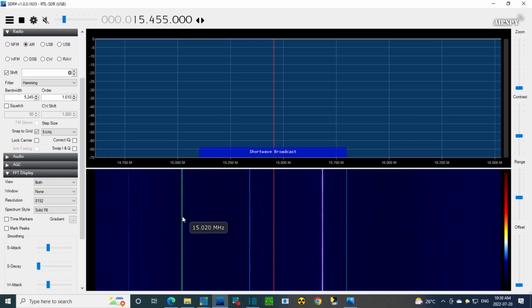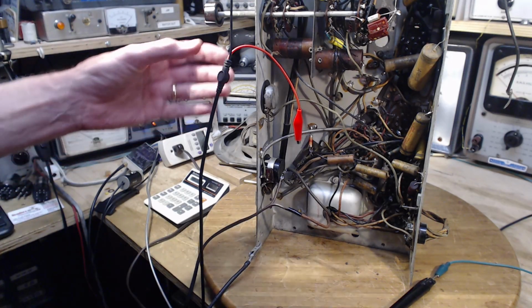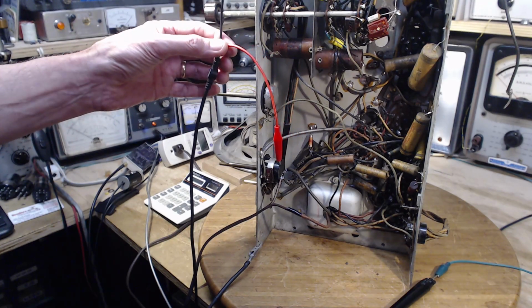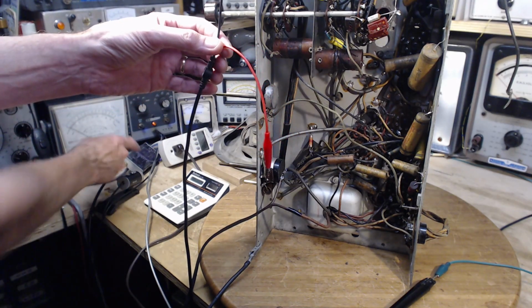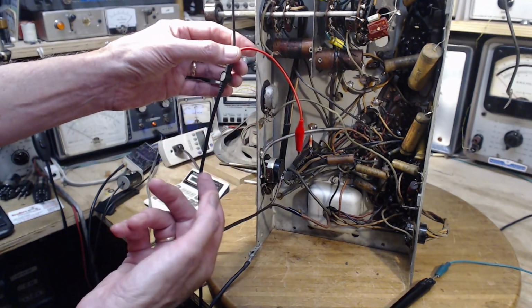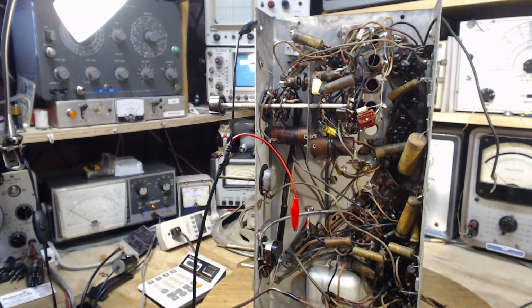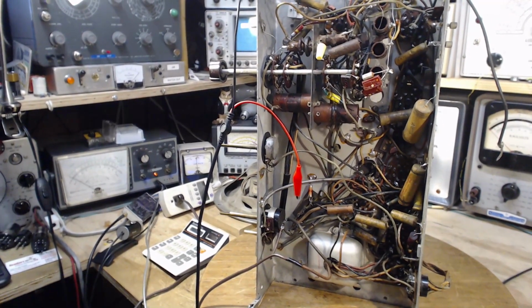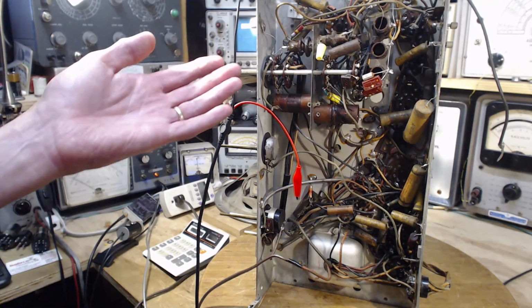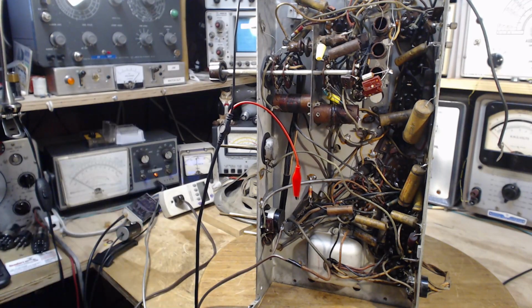Let me show you how I'm doing this antenna here. Nothing fancy whatsoever. So this is the lead going to the SDR radio over here. This is the antenna lead, if you like. It's not even connected, right? And the ground, I just clipped it to the chassis for no really good reason. You don't even need to do that. Sometimes I just lay this wire on the bench over yonder and it can pick up the local oscillator because they're generally quite strong.